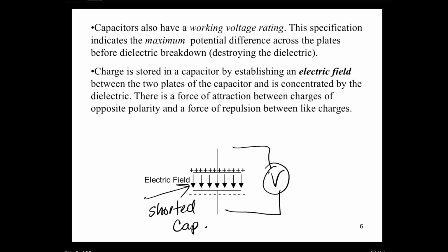And there should never be electrical current flowing between the two plates, right? But just like in lightning strikes and so on, if the force is high enough, you can break down any insulator and it will conduct. And it's the same idea with a capacitor, and that's what gives a capacitor a maximum working voltage. So it's something to be aware of whenever you're working with them.